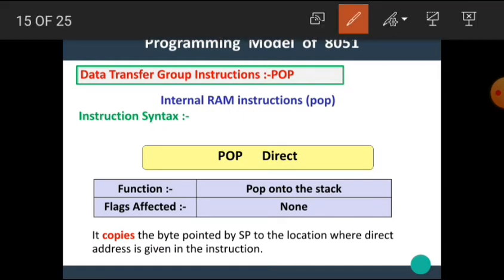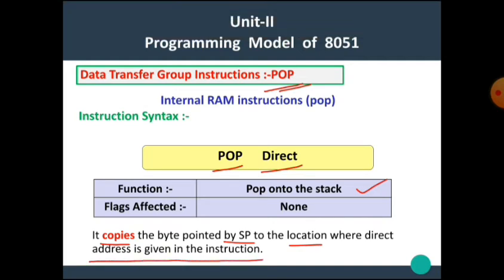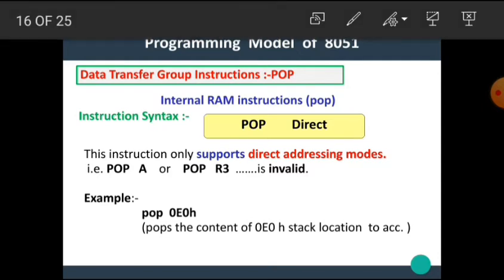The opposite instruction of push is the pop instruction. Its syntax is pop direct. The function is pop from the stack. It copies the byte pointed to by SP to the location where the direct address is given in the instruction. For example,